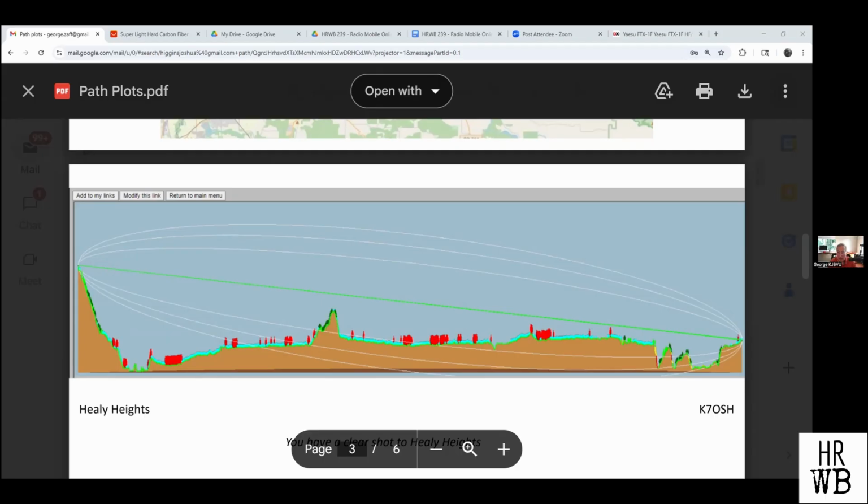Interesting. So if you had a choice of having an obstruction anywhere in the Fresnel zone or not, actually having some obstruction could be beneficial. It's better to have a Fresnel zone obstruction. Wow. In engineering, we say that it's dangerous because due to inversion, if the temperature gradient changes, you may have a different refraction that will make it so that at one hour in the day, you are in the first Fresnel, but later in the day, you are in the second Fresnel.